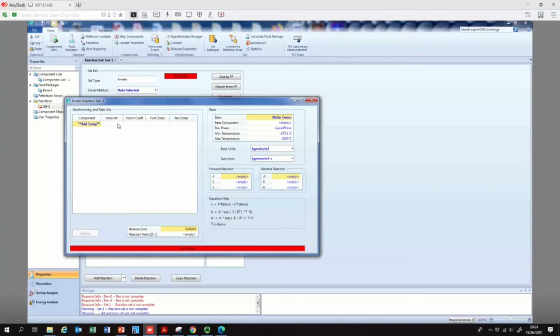We have to add the fluid components, select a suitable fluid package. And then once we're happy with the fluid package, then we have to think what the different chemical reactions involved are, and then we have to add those reactions. And obviously, you cannot just add the reaction. You should have other fine details like the rate of the reaction. Obviously, it's connected to your activation energy, whether it's a first order, is it a catalytic reaction, or what type of expression we need.